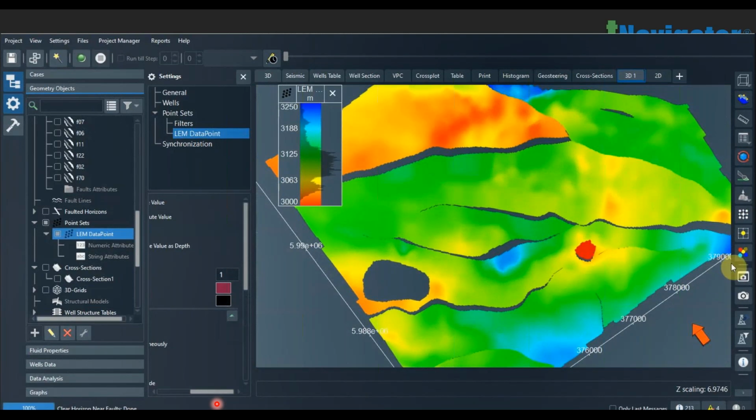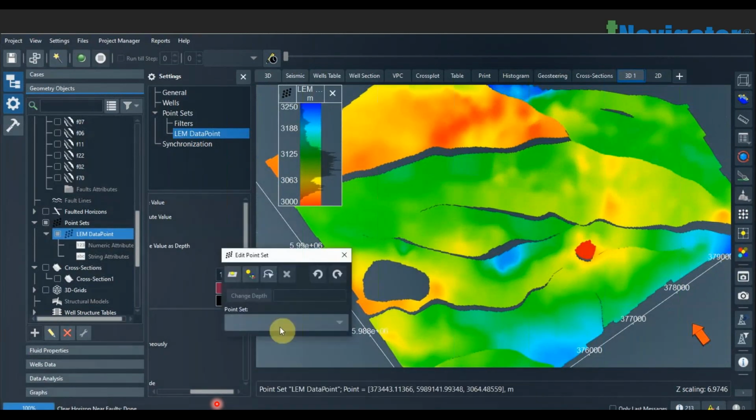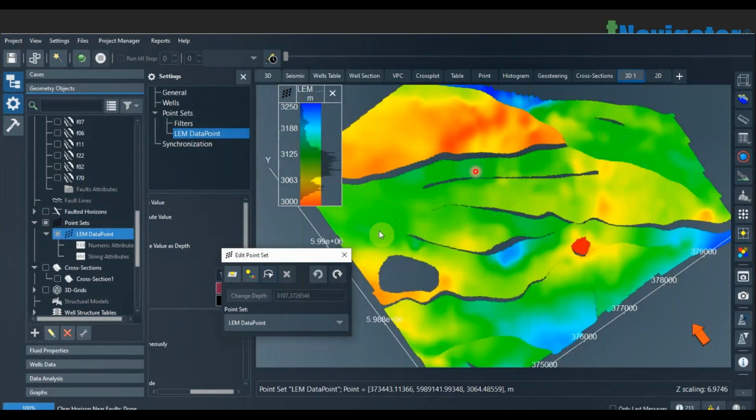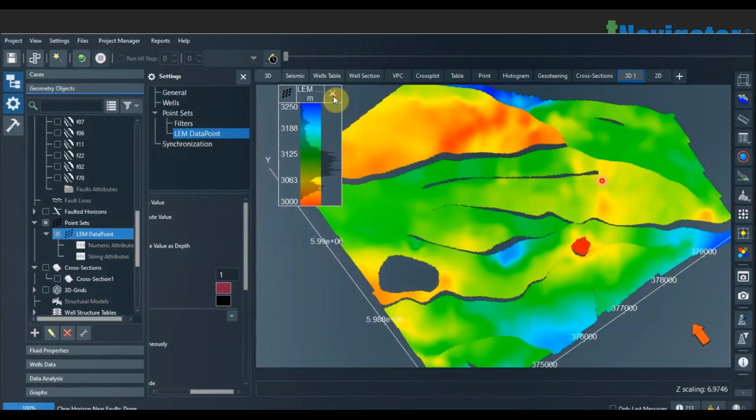And let's say you have a new fault interpretation coming in, or let's say you don't have a fault interpretation, but you know, based on your production data, there should be some barrier between this area and here. Instead of creating a fault from scratch, you can easily just create a blank space here that acts like your fault, right? And then clean the area here, and then use this as an input for your 3D model later.